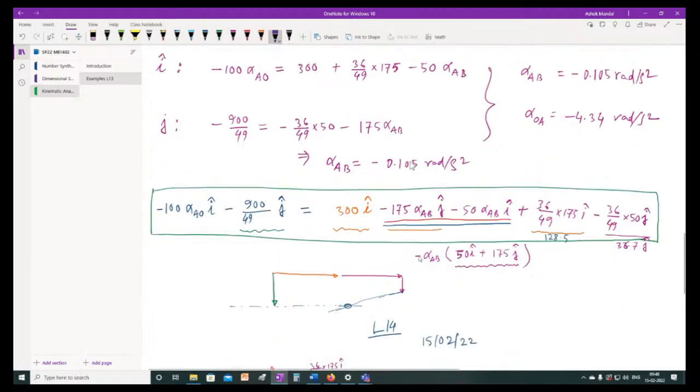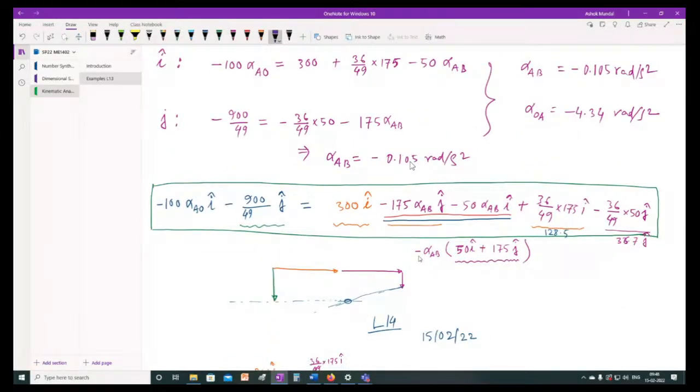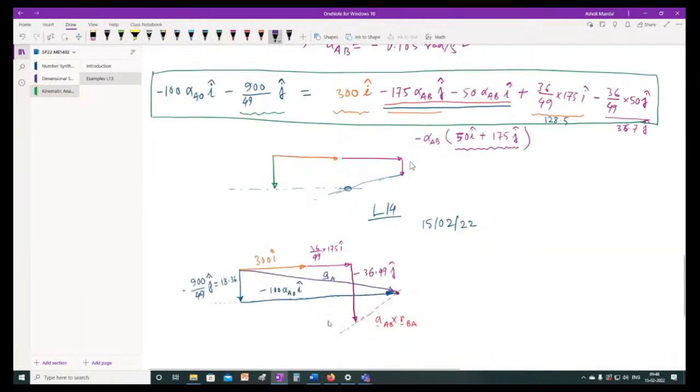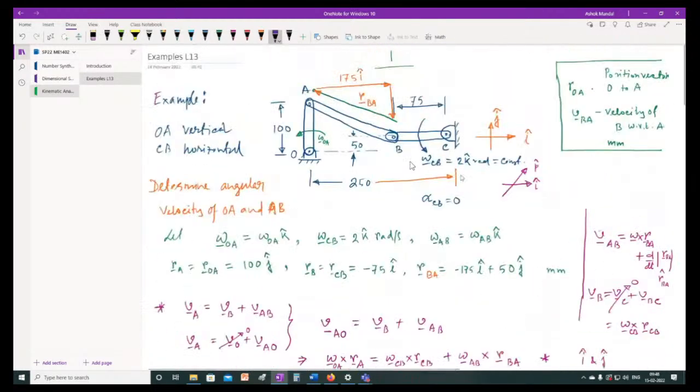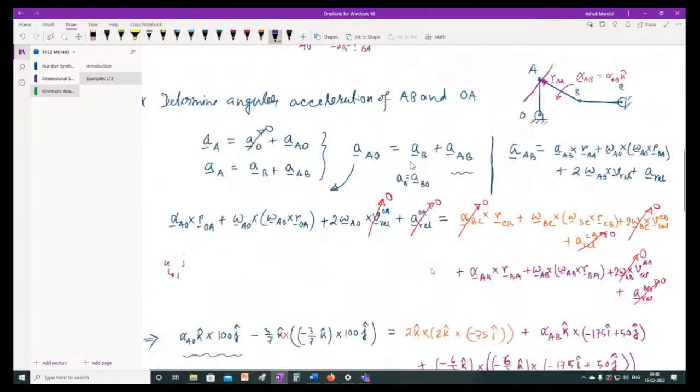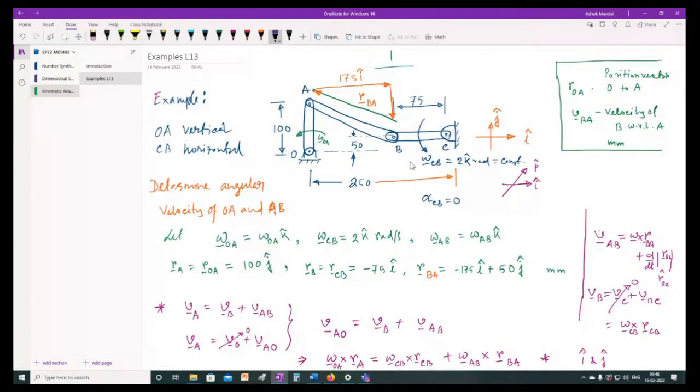The advantage is, as I said many times, when you draw an acceleration diagram or velocity diagram, that diagram is valid for that particular crank angle. Okay, how much the crank has rotated, it is valid for that only. In the next instant, when the crank is rotated to some other angle, the position of these links will also change. Depending on that, the velocity and acceleration of these points and links are also changing.